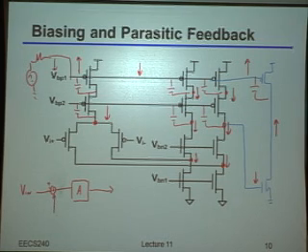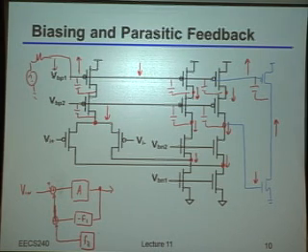Okay? So let's draw, again, our generic structure. Okay? So as an example, I have one feedback connection, which is a negative feedback connection through that F1. But notice that I put the negative sign there. But now what I'm going to do is add to it a positive feedback F2. Okay? Which, by the way, is a really good model for the situation we have here, right? Because we have two paths, one with negative feedback and one with positive feedback. Okay? So if I want to make sure that I actually have net negative feedback, what do I have to make sure is true? What condition do I need to have with these loop gains here?